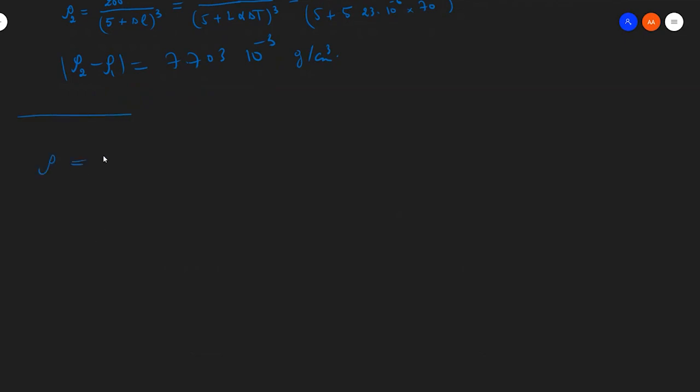You have rho, which is m over v. If you have seen in your lecture, or probably have seen this in the lab, you have rho is changing because of the change of v, and m is not changing. I will write it like this, m v exponent minus 1. So you have something v like this. If you remember in your lab, in 102 lab, you have studied this. Delta rho over rho is equal to delta m over m, but delta m is 0, it does not change, plus this one, delta v over v. And you have, because this one is minus 1, it becomes minus 1 here.